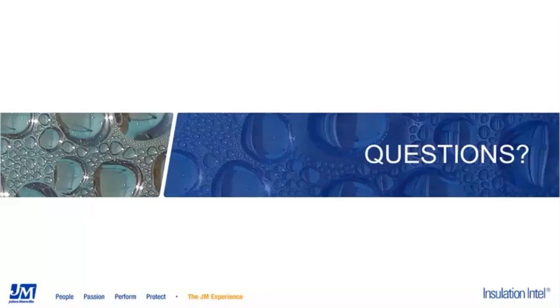Get the vapor retarder as continuous as possible, seal around the valve stem, and then this is very often overlooked, especially with chilled water that's in hidden spaces of buildings, but a good inspection and maintenance program is important. A periodic inspection of known weak points like penetrations is important, and repair of damage to the vapor retarder, or even if it's not damage, if it's just a place where it's pulled loose from a valve stem or something, that kind of area can be repaired.